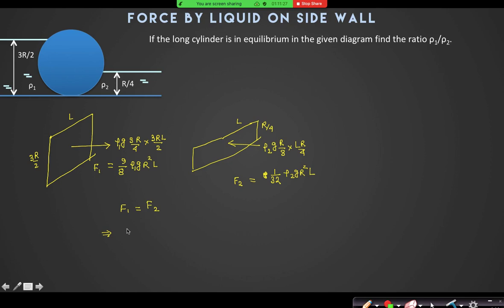Sir, for equilibrium, we are only considering translational equilibrium and not rotational equilibrium. Rotationally, it is always in equilibrium because all the forces will always pass through the center, so torque is not there. Sir, in the previous parts, when applying torque we took the average pressure to be at height h by 3. But here, if you take that, we are not getting equilibrium.